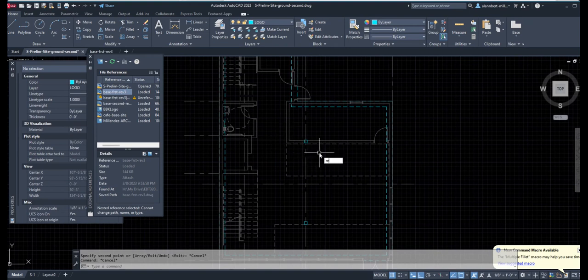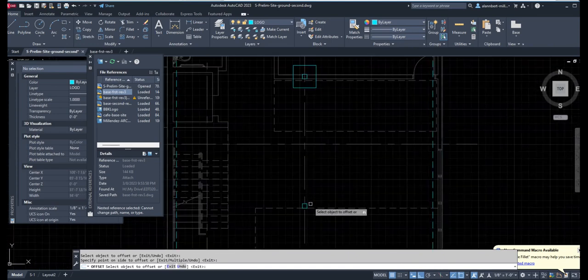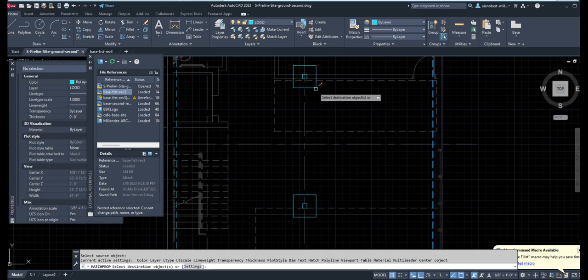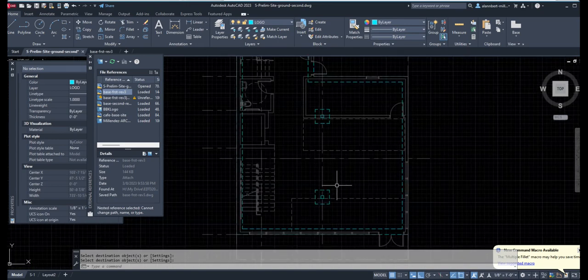Okay, and that's typically a square, and it would also be dashed, indicating that it's below the ground. So this is your foundation footing, and this would be your continuous wall footing or a strip footing.